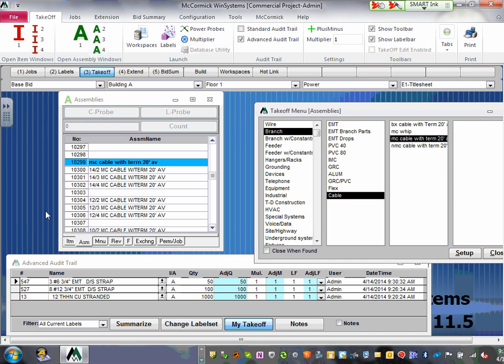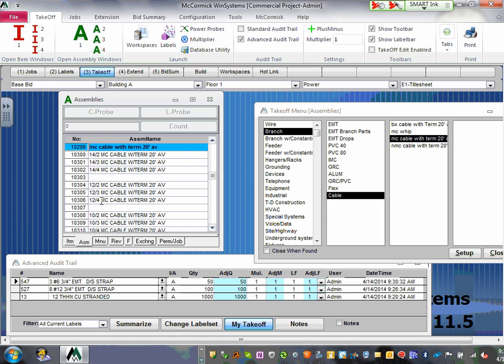That MC cable, I have 14.2, 14.3, and 14.4, Adam. Most likely, guys, you're going to be moving with 14.4, exactly like this one. Why 14.4? 14.4 will give you 3 circuits and a neutral. So as you move from here to here to here, you can pull 4 circuits out of the same conductor. What does that do for you? It saves you a lot of money and time. 3 circuits, right? 4 conductors, 3 circuits. I don't like to use 14, but we don't use 14, right? We use 12. So I'm going to go all the way to 12.4.